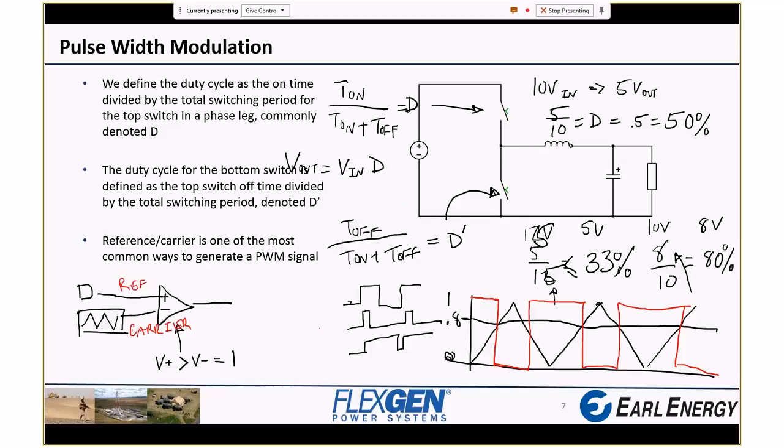Depending on circuit conditions, you could be changing this reference continuously. Say your input voltage was a battery that was charging and discharging, due to some external circuit. You could modulate this reference in order to maintain your 5-volt output.